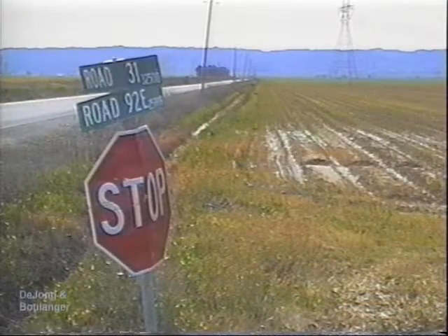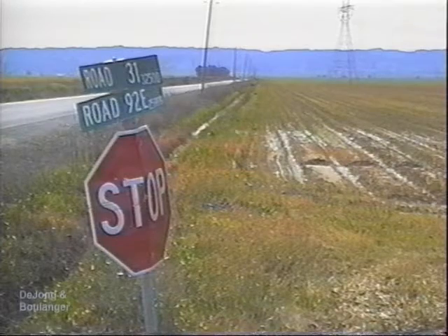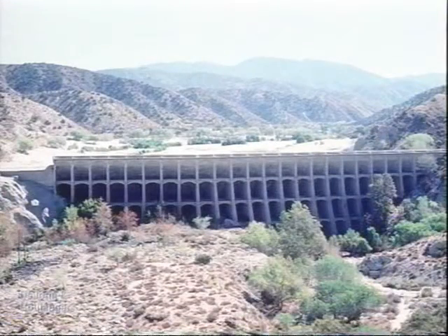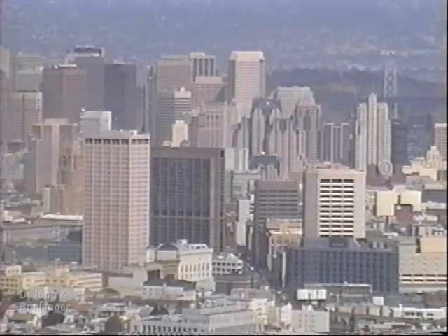For example, the design of a county road may only require explorations to a depth of 20 feet, while the design of the foundation for a high-rise may require knowledge of soil characteristics to a depth of a few hundred feet. At remote sites, all the necessary information may have to come from new soil explorations. In highly developed areas, the extent of soil exploration may be reduced based on information from the surrounding sites.